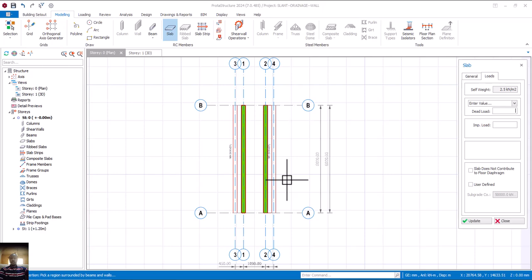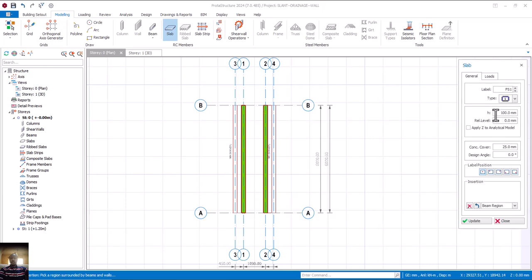If it's a good grade of concrete to use, let's say you are using a ratio 1:1.5:3 or 1:2:4, whichever one, it's a good grade to go with. So even though you make the depth 75, there's no problem. I mean, talking of this place. The most important thing is the grade. And after all, this particular one, I think it's going to be reinforced.